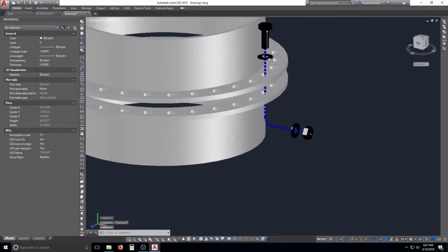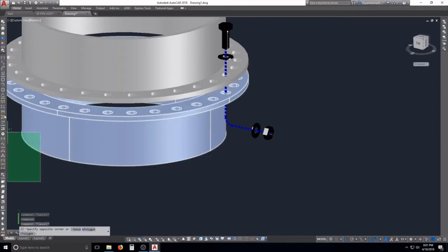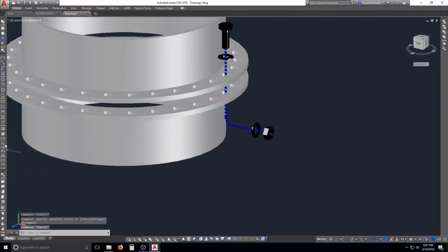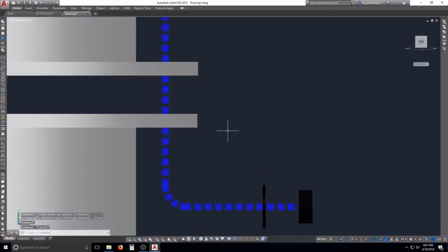Now you say, well, what about the arrows you had in there? Fret not. So what you do to get those in, and that's just something I recently started doing, we need to go in the front view. And from here, all you do really is just draw any shape, polygon or whatever that resembles an arrow, and then you press pull it, and there you go. So we're going to just go something like F8, turn that on there.